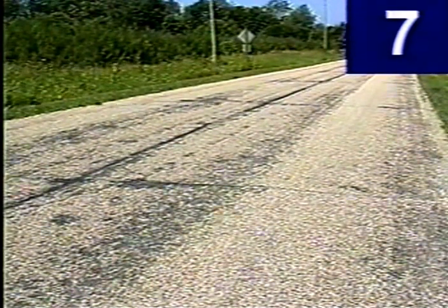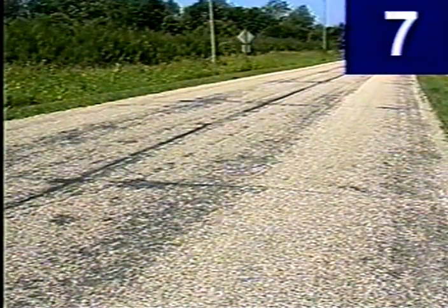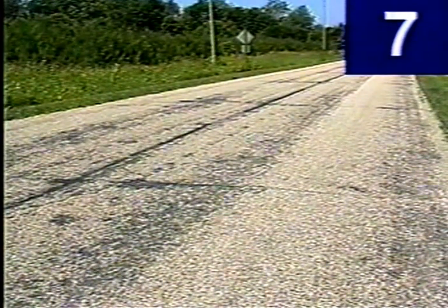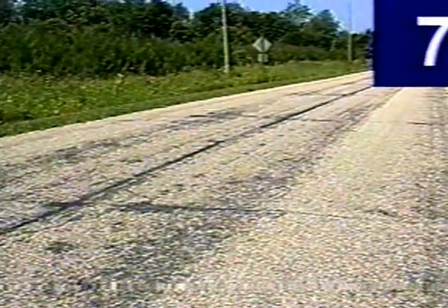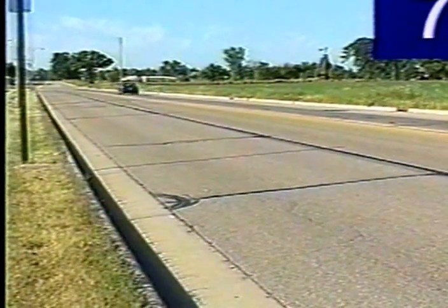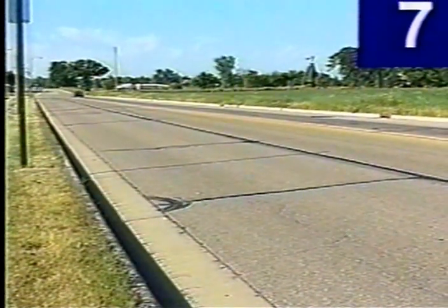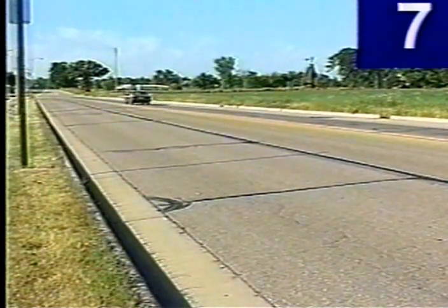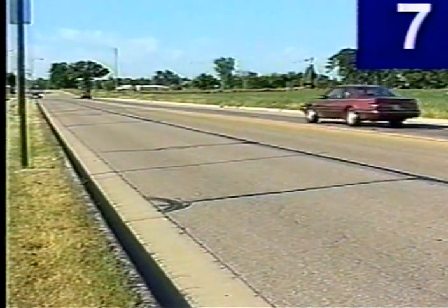This is an example of a pavement that has had a recent seal coat, but you can see it has some life on it now. It's not a brand new seal coat. Some of it has worn off under traffic and probably snowplow action. You would want to consider looking at this and keeping the crack sealing in good condition. Another pavement where we've had cracking, and it's gone to the point that you definitely want to have a good aggressive crack sealing program, but it's still in good shape. I would rate this pavement a 7.